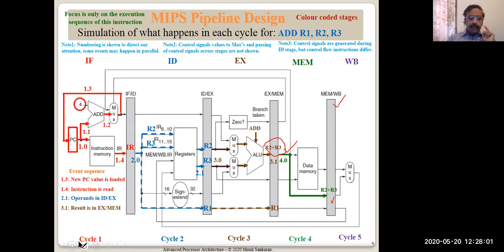And what else needs to be done? Now, I don't want you guys to miss out on something else. You should do one more thing, pass on R1. Okay. So this is the job done here. Data memory, nothing happens. It is not doing anything with the data memory. So no data memory access is initiated. These values are not read by the data memory. So it's all happening very intelligently based on the instruction. The flow happens. Okay. It's very interesting to watch how it is really implemented inside a pipeline. That's why I took pains to simulate it and show it to you.